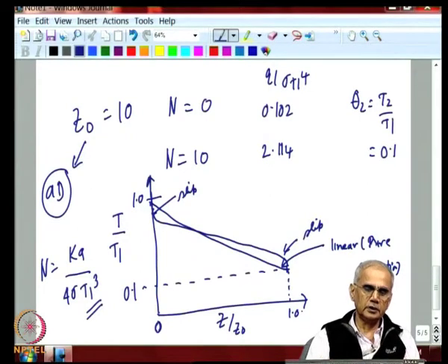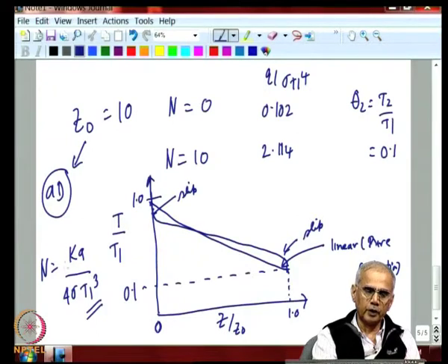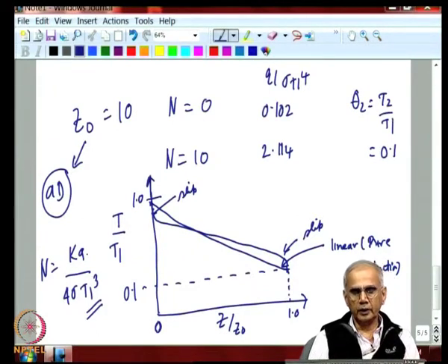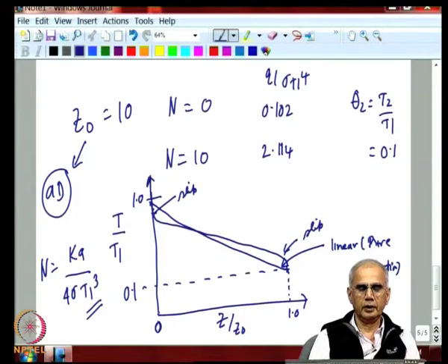The second part, of course, is the molecular conductivity of the gas. That, of course, will make conduction more important if K is large, but the role of the absorption coefficient is slightly counterintuitive, because you would have thought that a gas in which the absorption coefficient is large will be the one where conduction is less important. Okay.